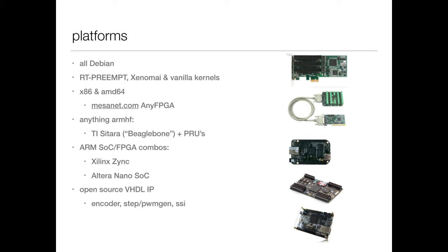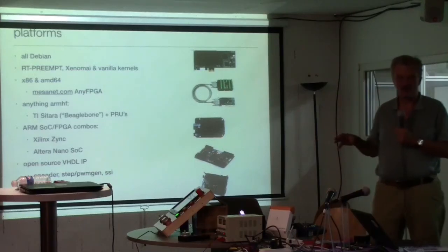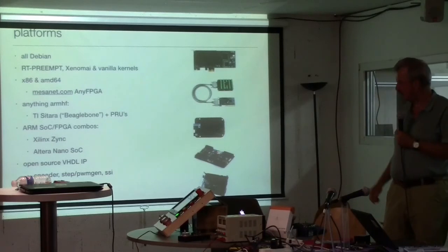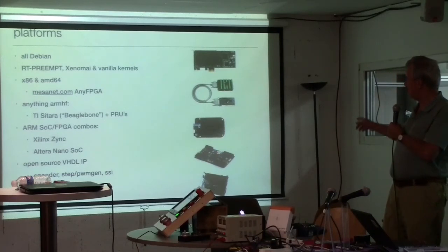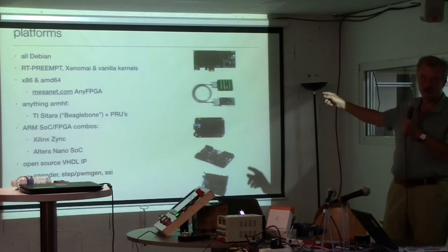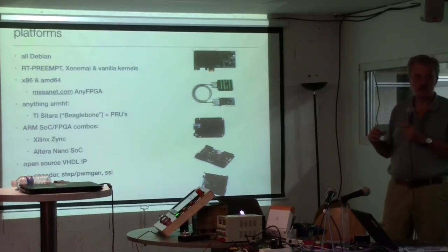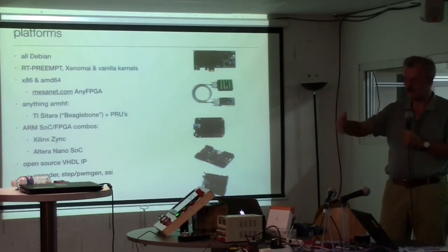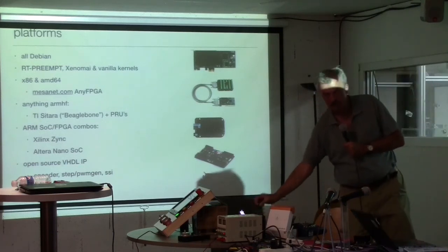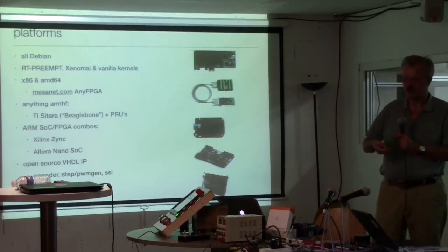So one form of peripherals which are very popular both with LinuxCNC and Machinekit are the products by a Californian company called Mesa. What they produce is cards which embed an FPGA and can be connected to what they call daughter boards over a standard bus.